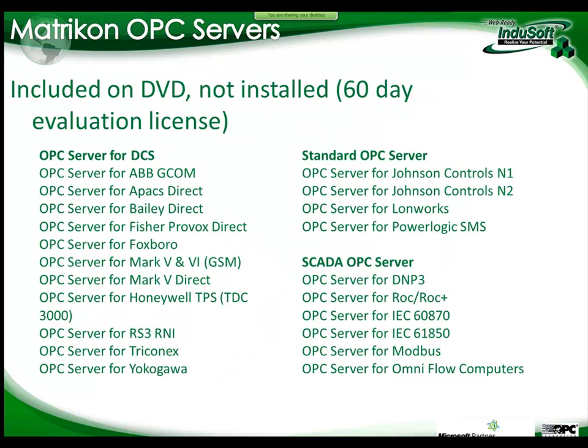So as part of the InduSoft solution to allow you to integrate with DCS systems, we offer some OPC servers from Matrikon, and more specifically the OPC server for DCS. So you see here connections to Foxboro, to Yokogawa, even to ABB, to Honeywell. You've got the TDC 3000 or the Experion. So we have the OPC server to talk to all these different DCS systems that we can resell in our partnership with Matrikon.